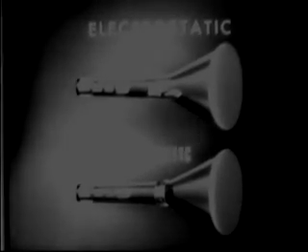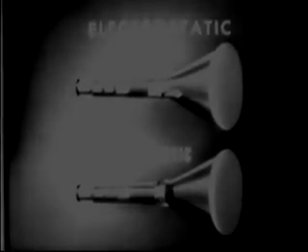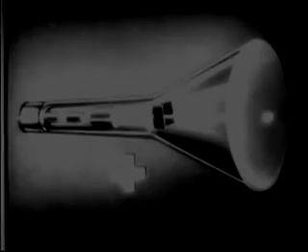First, to review what we know of the electrostatic tube. At the rear end of the tube is an electron gun, composed of a heater, cathode, grid, and focusing anodes. The cathode, when heated, gives off electrons, which are formed into a stream by the grid. The anodes accelerate the electrons and focus them into a beam. The beam bombards the fluorescent coating on the face of the tube and causes it to glow with a bright spot of light. These plates deflect the beam horizontally. When positive and negative voltage is applied alternately to the plates in the form of a sine wave, the beam is swung back and forth like this.